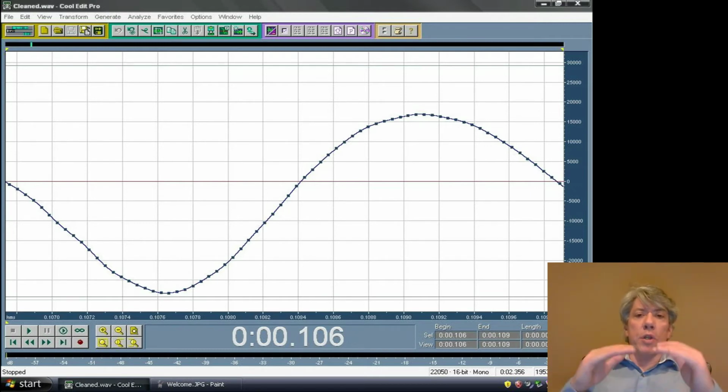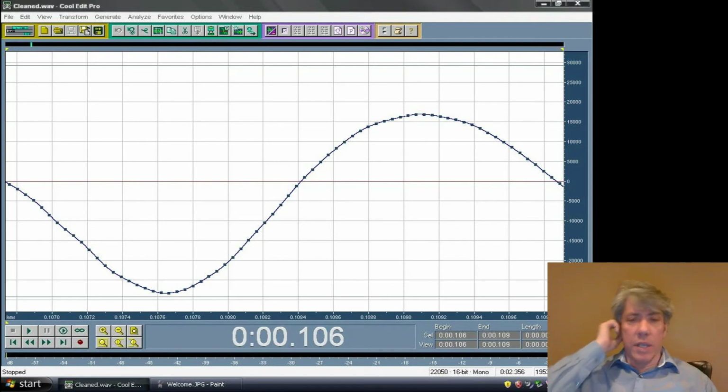As far as measuring the amplitude, what's the analogy there with industrial systems? Well, let's go back to our furnace, for example. There you're measuring temperature, and the question is, how fine a temperature difference do I need to measure? 1 degree Fahrenheit? 2 degrees? 10 degrees Fahrenheit? Well, if you're designing your furnace to operate at, say, 2,000 degrees Fahrenheit or so, probably 1 degree is an adequate resolution. Do you care if it's 2001 versus 2,000 degrees in the furnace? Probably not. Right? That's fine control.